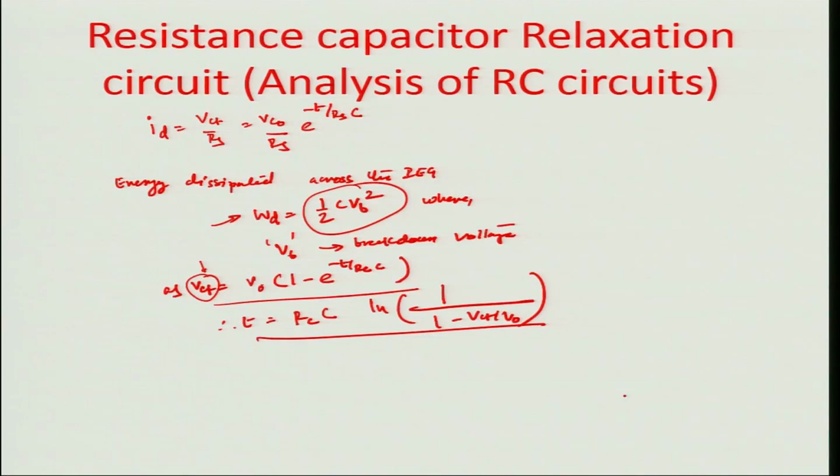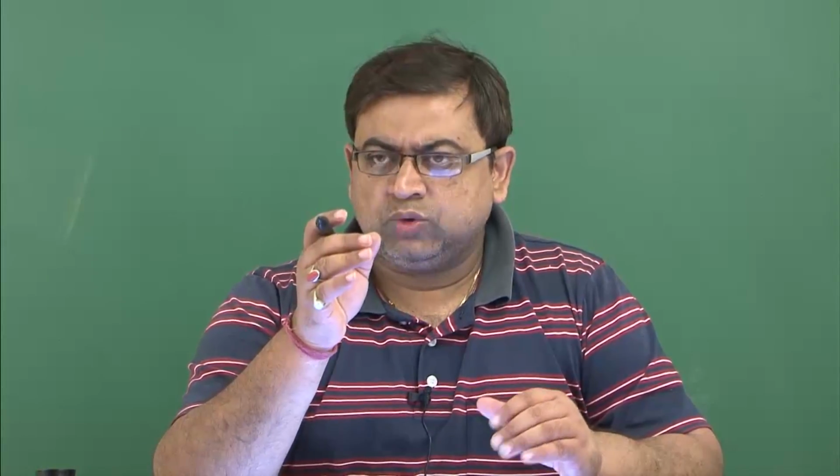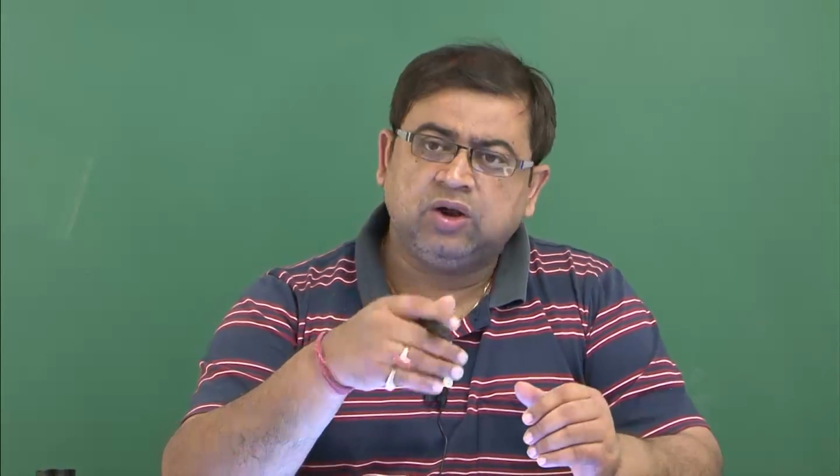So from this we can actually have an idea of the sparking frequency, because as you have found in the earlier trend, the signal goes all the way up to 72% of V0, or the source voltage, and then falls down. The falling down of the sparking time is very short in comparison to the charging time. So most of the total duration of sparking is covered by the charging time, and there is very little value that the sparking process itself adds to the overall time.